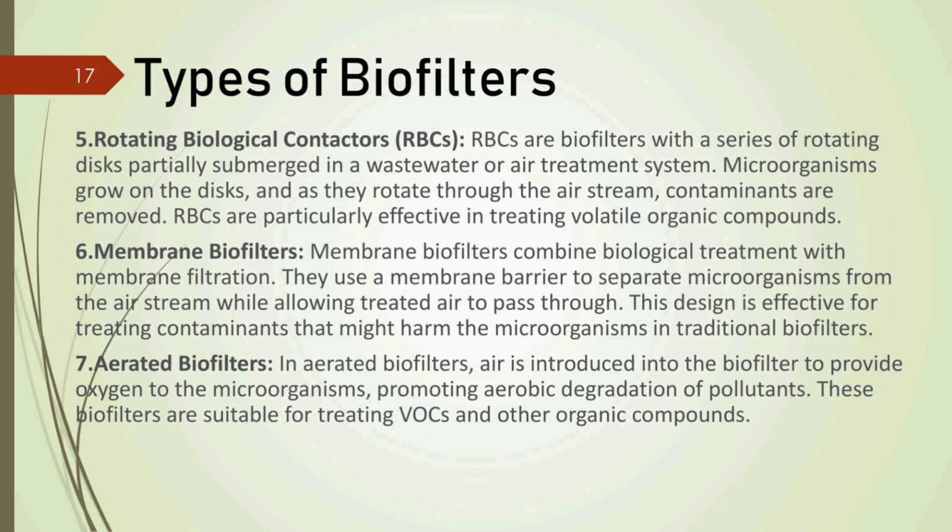RBC is a biofilter with a series of rotating discs partially submerged in wastewater or an air treatment system. Microorganisms grow on the discs as they rotate through the air stream. Contaminants are removed. RBCs are particularly effective in treating volatile organic compounds.